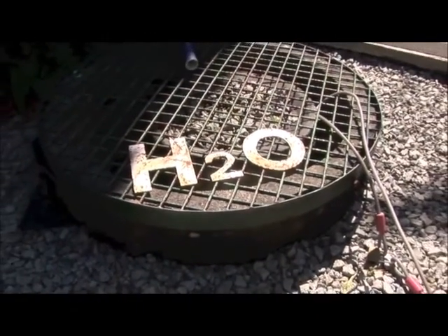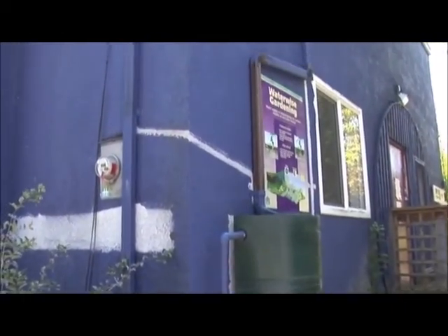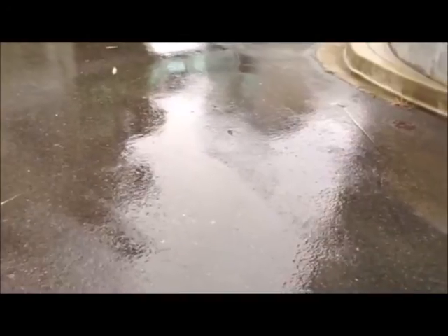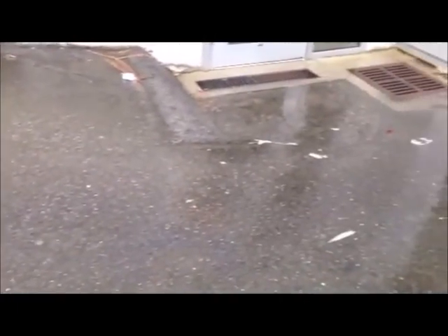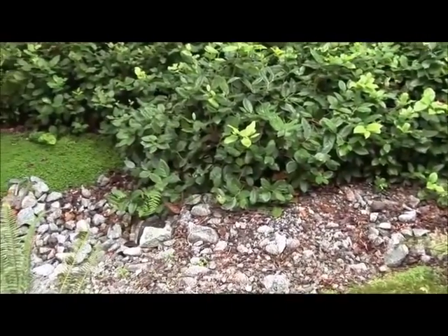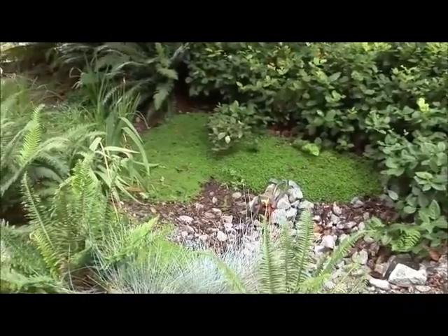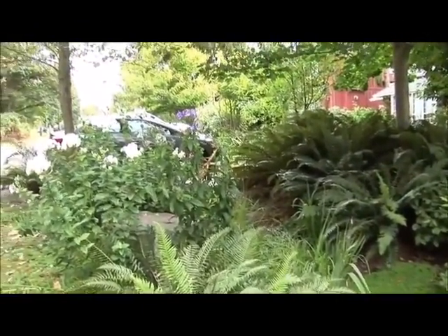There are many designs to better manage stormwater on a property scale. This can be done both in new construction and in retrofits. Rainwater becomes runoff as soon as it hits an impervious surface, such as a roof or a driveway. By retaining, reusing, and infiltrating rainwater on their property, homeowners can reduce the amount of water that makes it to storm sewers. This mimics Mother Nature, where soil and vegetation slows the movement of water. It also allows it to infiltrate into the subsurface.